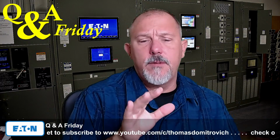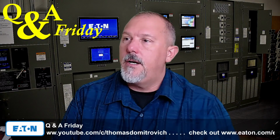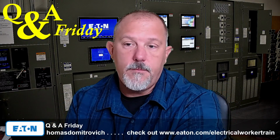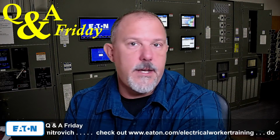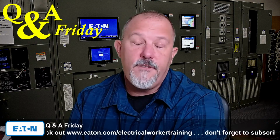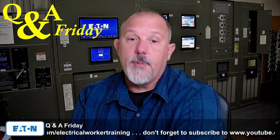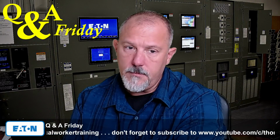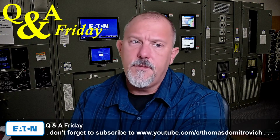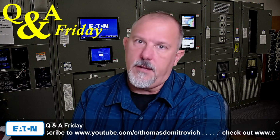So here's the thing. One thing I would say, if you're dealing with a small piece of equipment, you've got to look at where you're at in the circuit. 10K is like a minimum requirement for a lot of things. 5K might be a minimum requirement for certain types of equipment, appliances, etc. But the conductor that you're on the tail end of, if it's a small conductor, adds a lot of impedance and it really knocks down the fault current.